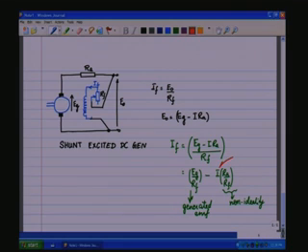So, the variation in the load is going to cause a variation in I F, which means the flux here. Now, the flux is directly also going to affect E g, which is going to affect your regulation. Therefore, the regulation in the shunt machine is going to be much poorer.